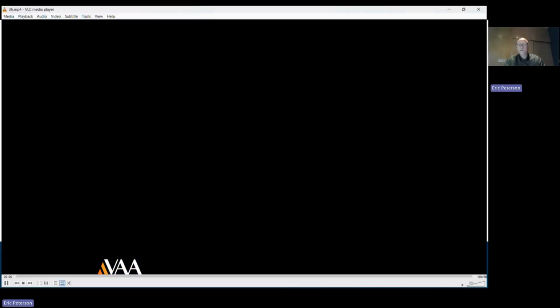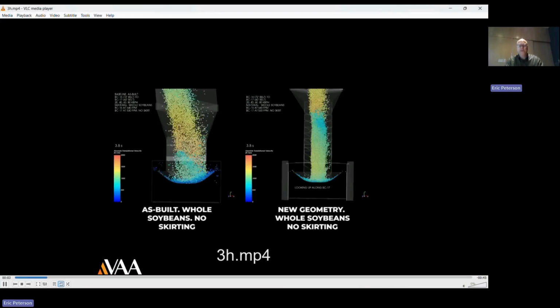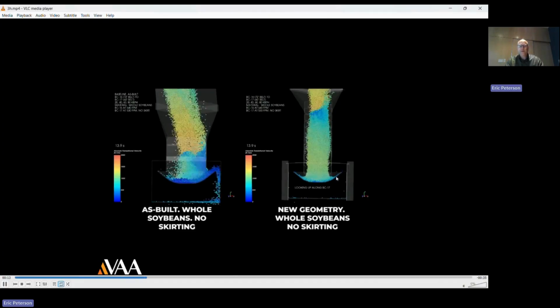And then another view of this side by side. And in both of these views, by the way, the skirting is still turned off. So we did that to see the more optimum loader design. You can see there's still spillage on the outside, but with the skirt boards close to the edge of the belt margin, like they're usually designed, we'll prevent that minor spillage. And that's really what they're intended for.